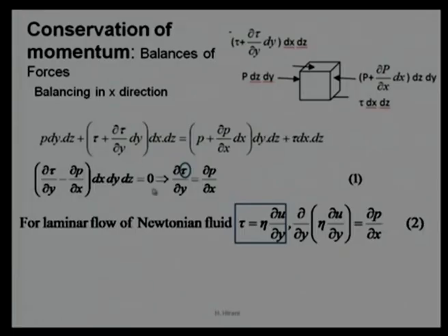If I use this equation, equation number 1, we can get pressure in terms of velocity and viscosity. If viscosity is 0, we know the pressure will not be generated. Or if there is no relative velocity or no velocity gradient, then again there will be 0 pressure. So, that is why for hydrodynamic action we require both. We require viscosity, we require velocity gradient, we require relative velocity. If there is a relative velocity, velocity gradient will come.